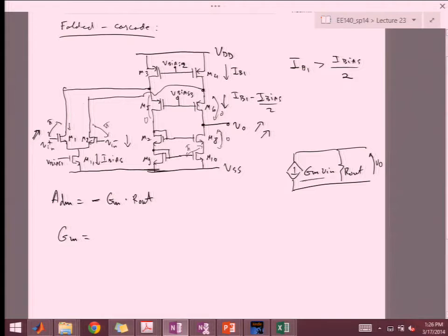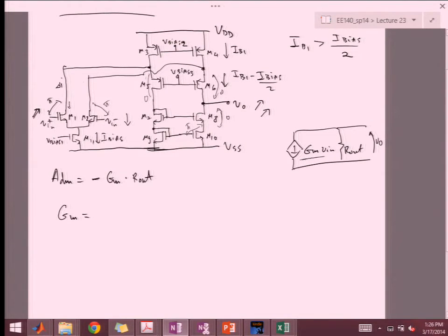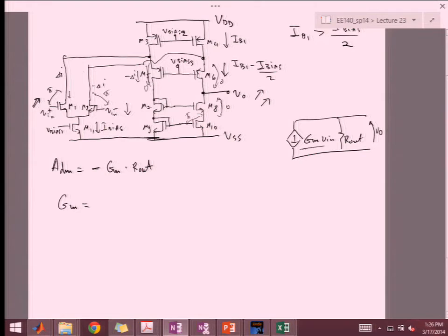So whatever delta I you had here needs to come from this path down, right? So there's minus delta I here. Correspondingly, on this branch, if this one has minus delta I, then this branch over here will have plus delta I. So that transconductance that shifted the voltage to current, that current is now going here.